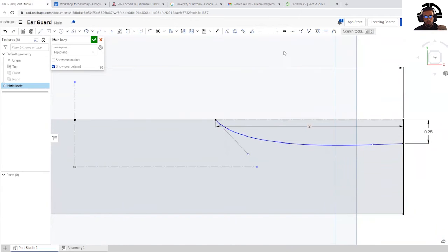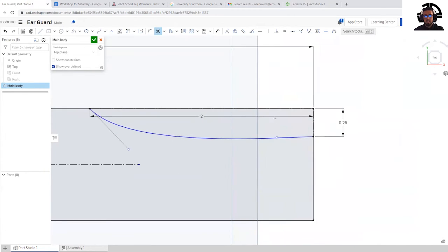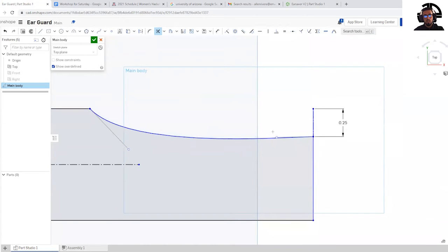So I want to make it so that these two are my only lines combined. What I'm going to do is use this tool called the trim tool, which also has a hotkey of M, and I am going to remove this line that connects from this point to this corner and this line that connects from this point to this corner, since I want this to be the line that takes over. So I'm going to click on trim or the hotkey M. I clicked M and then I delete that line. I delete the construction line because I no longer need it. And I will also be deleting this line so that this becomes the line that we work off of.